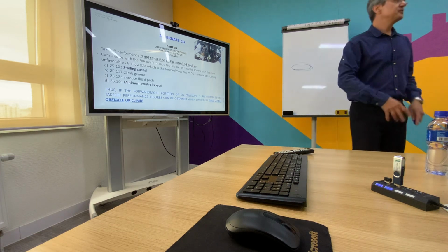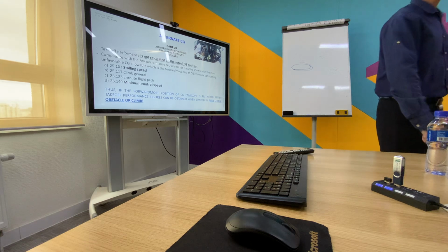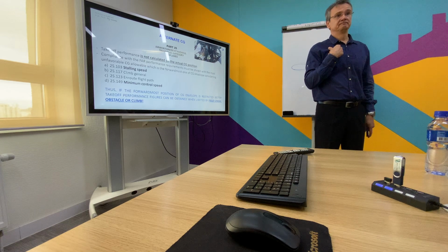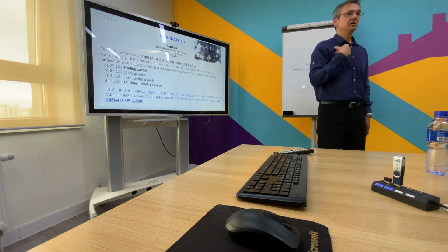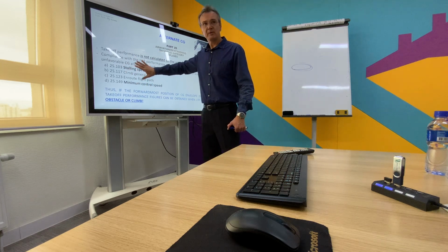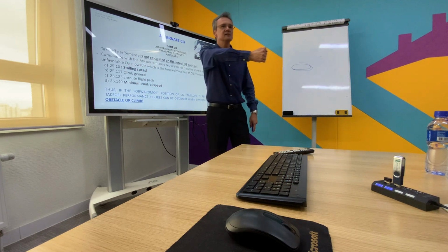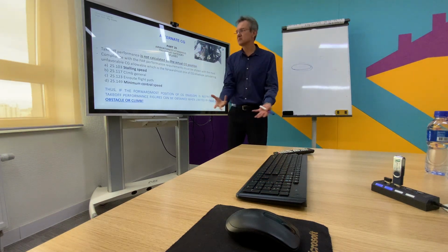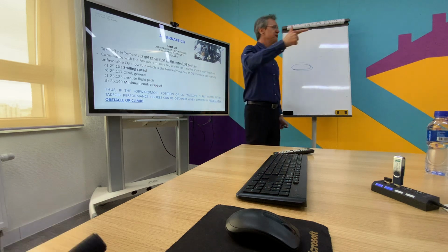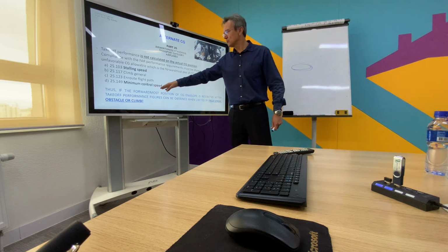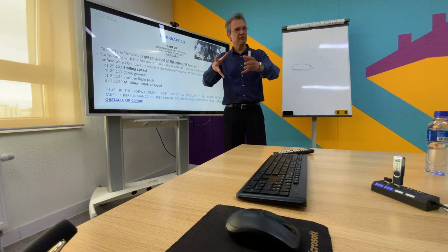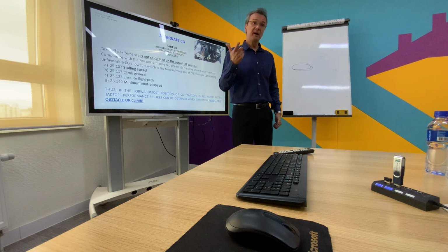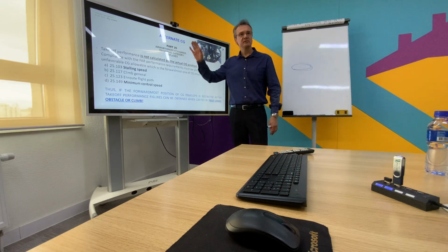Test pilots went to the authorities, ANAC, FAA, EASA, and said, I want to certify a new CG for takeoff. So-called alternate CG. We're going to get these parameters and bring the CG aft. And we will certify, we will prove, we will show to the authorities that we may get a different stalling speed and a different minimum control speed for this envelope, keeping this safe. And Embraer spent a lot of money to certify the alternate CG.